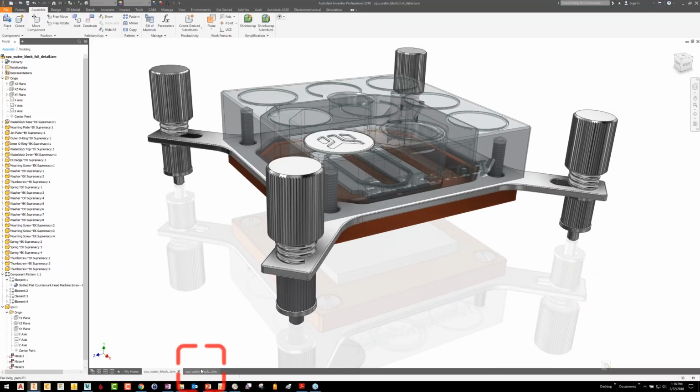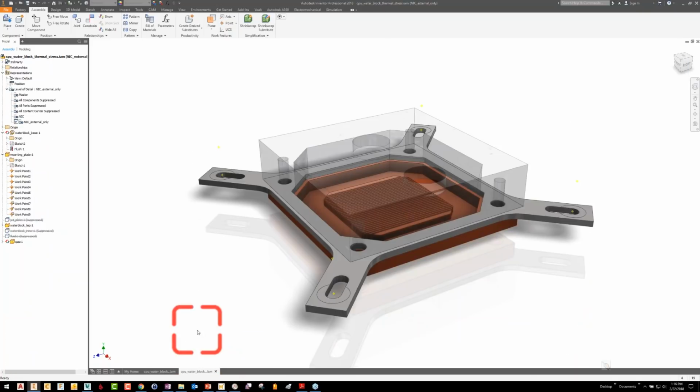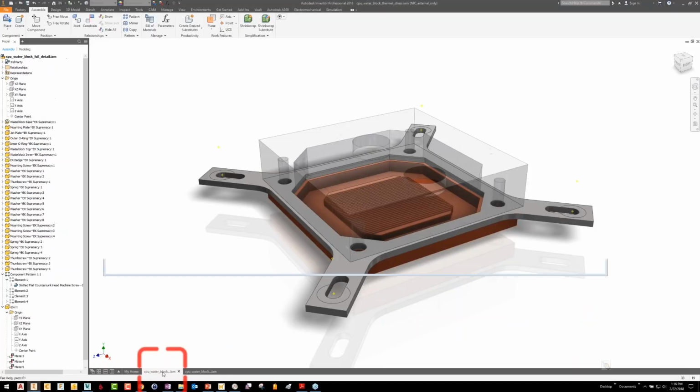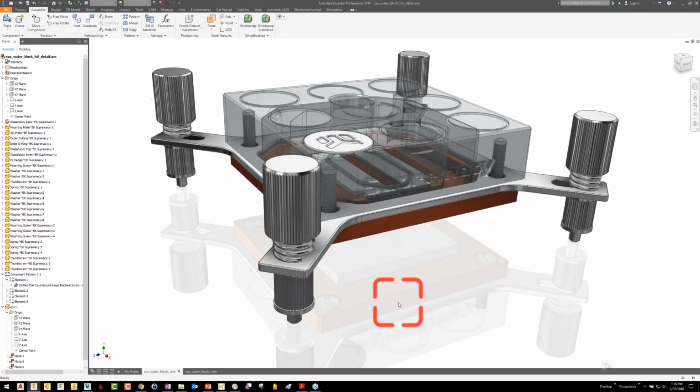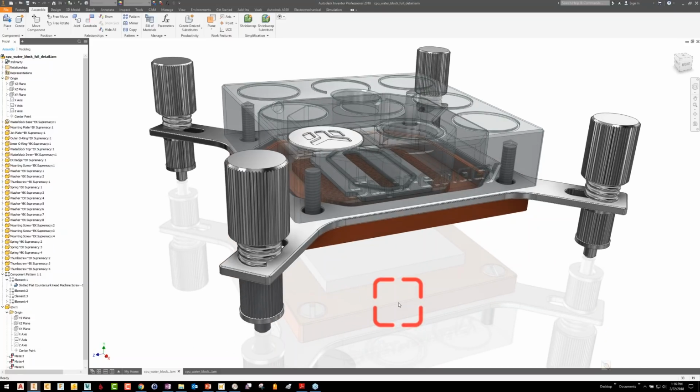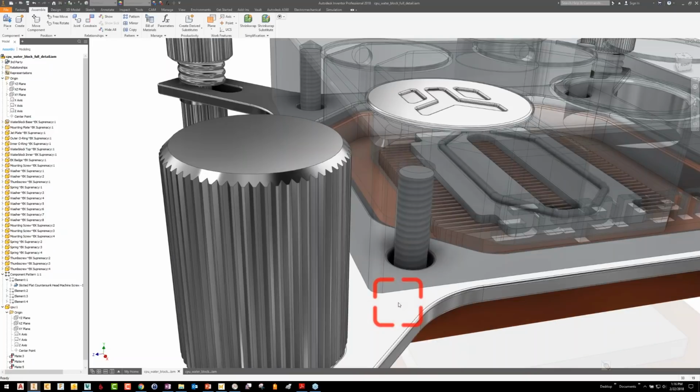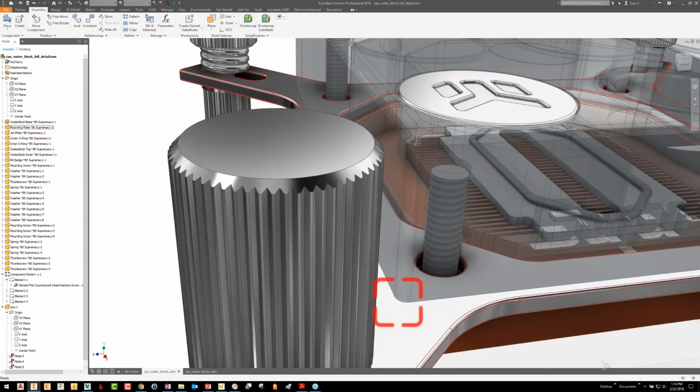And then you'll have a version that I've stripped down for simulation purposes, which is what I'm actually going to use for the model today. This kind of thing isn't uncommon and is usually a critical phase in the simulation process, determining what's important for your model. Little details on my thumb screw, for example, those little grooves. I'm not going to spend the computational overhead to try and include those in my analysis when they add no structural value and have no effect on what I actually do care about. So I would remove them.